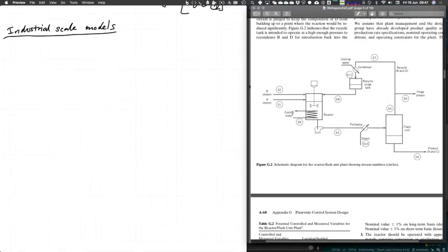Very unlikely that we will have good kinetic models, right? Definitely, we will have maybe some kind of idea of what the conversion should be. And I think a lot of people at this point are saying, but wait a minute, if we didn't have good models, how did we do the design in the first place? And again, the reality is that in many cases, the design of a process like this is done not by using detailed modeling, but rather by doing bench scale work and then scaling up those units, right?